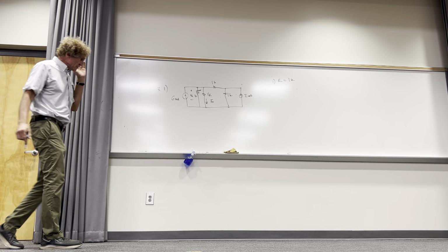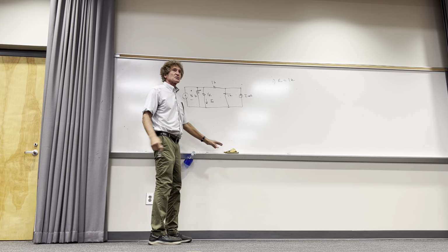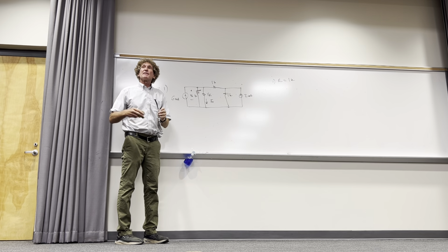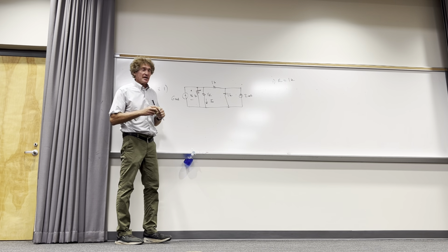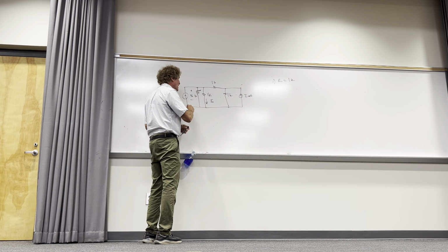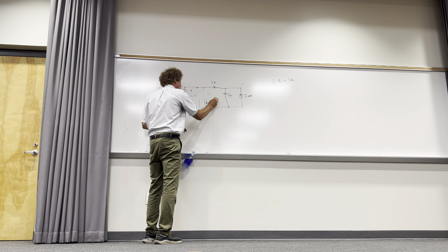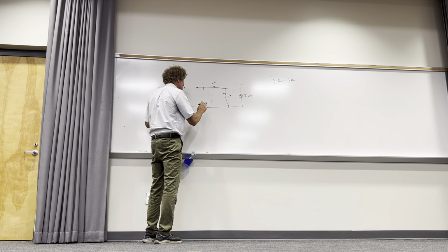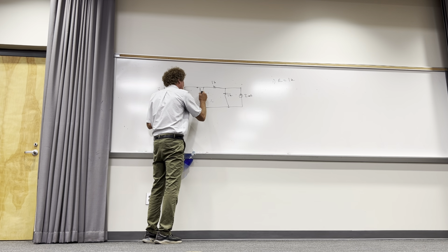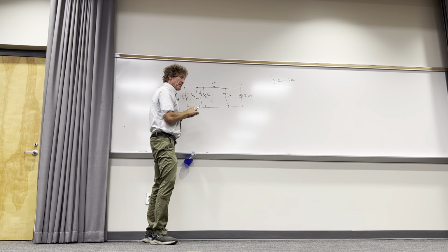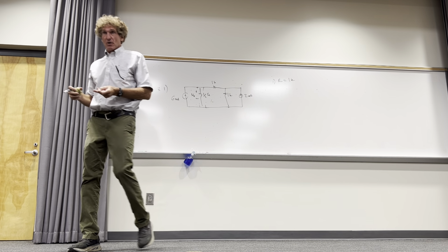Always use your brains. I mean, you're smart people. Don't make life difficult and don't be afraid. So obviously, if we're after the voltage and you see two in parallel, if all I care about is voltage, then just make it 1/2 K and put plus to minus V out, then it would be obvious. Do y'all see that?